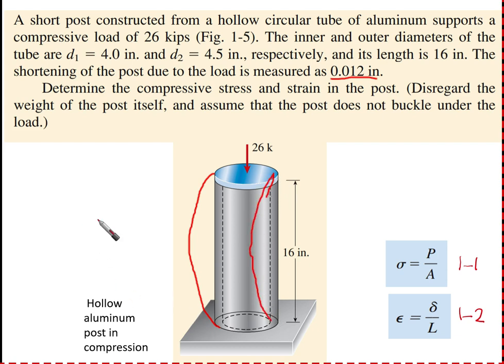So we are assuming that this is not a failure mode and we should not consider it. It will not buckle. All the load is going to be received axially, and the element is going to respond to this load through normal or axial stresses and strains.